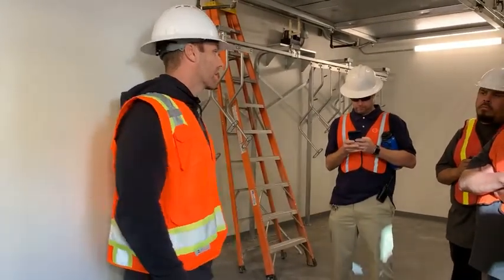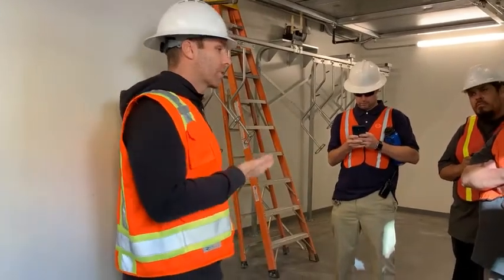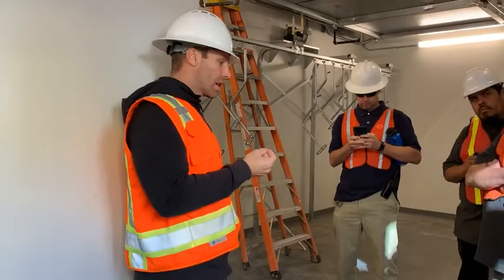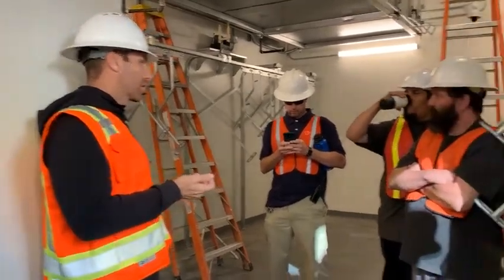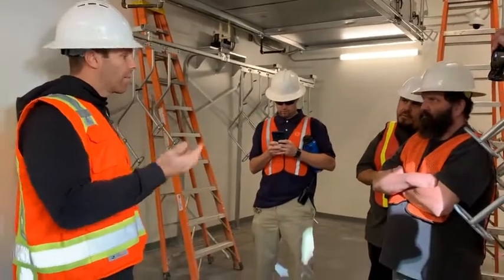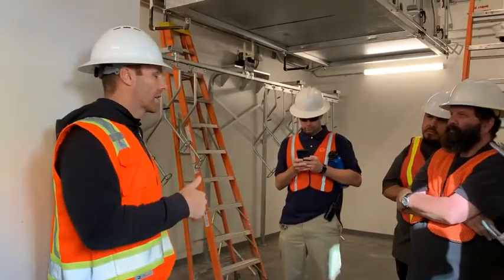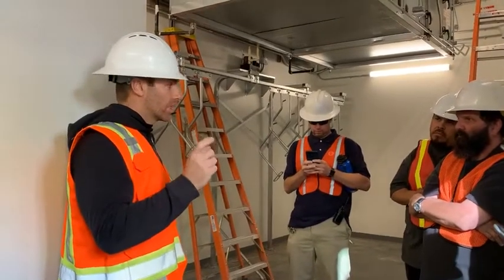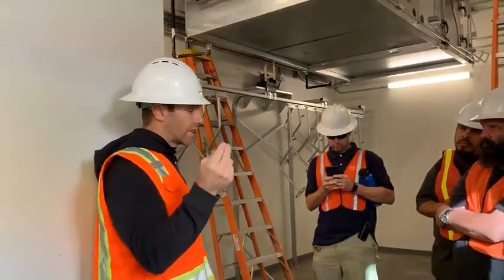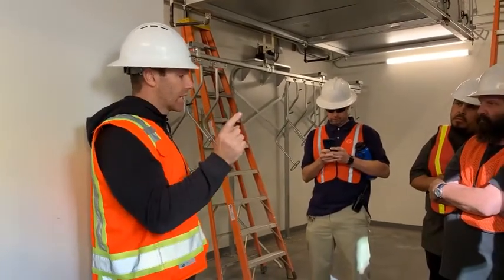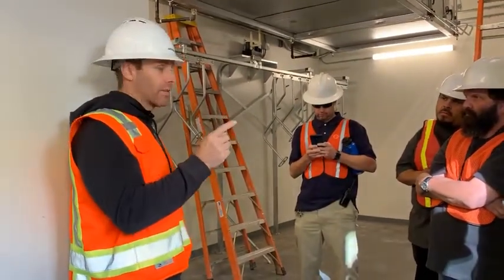Go to the LED fixtures. Our intelligent fixtures are really no different. The only difference is they get a command over 0 to 10, so there's no way for you to check the relay to make sure there's power coming out. Once again, you make sure there's power coming into the fixture, and not no power there at all. There's a little intelligent device there that's taking the Cat 5, and there are Cat 5 ports on it. And then there's 0 to 10 going between there and the driver.